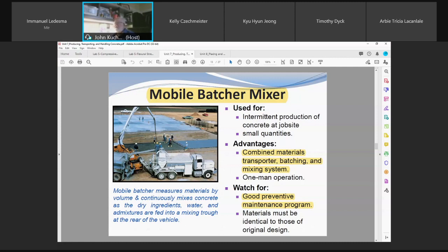The ready-mix producer has to go through a fairly extensive calibration. Okay, the scales, the plant, the trucks have to be approved every 5 years. The ready-mix producers have to have their facilities inspected by a qualified engineer. And not only the scales, the working operations at the plant, the revolving drum mixers. Are they turning at the right revolutions? Do they have a good system of fins inside the drums? Or are they all worn down?